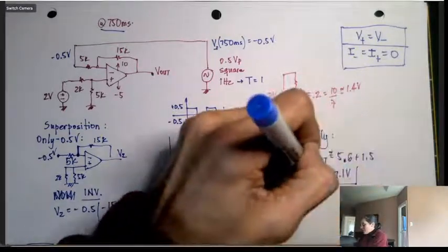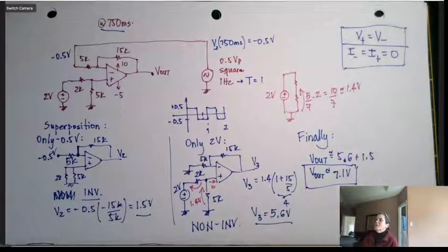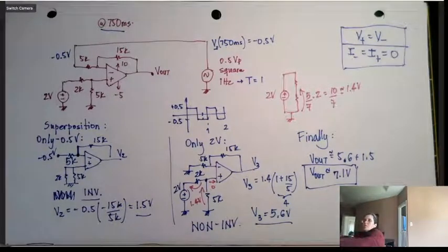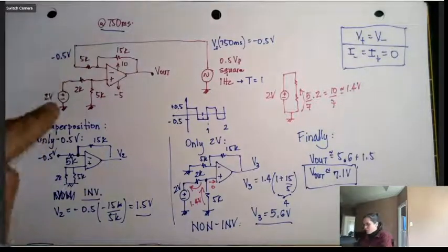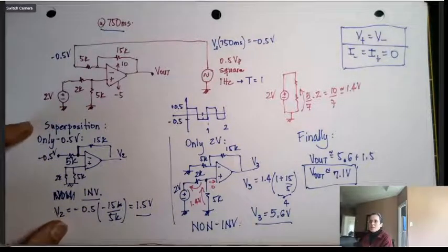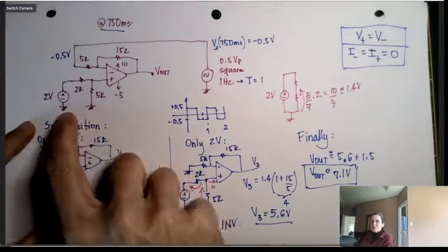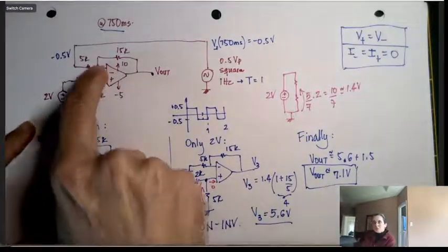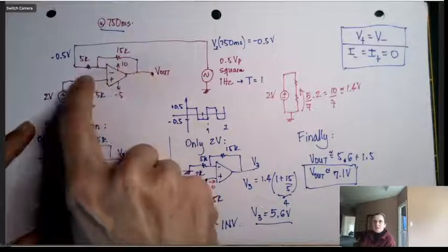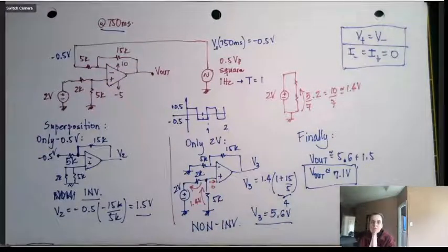I hope this helps, but if you would like me to answer any other questions, please let me know. I'm assuming we don't have a calculator. I'm also assuming we're going to do a lot of this. For example, if there are 2 power supplies, doing superposition from my perspective is simple, but you could have just put the 1.4 volts here and done KCL on it. So that's another way of solving the circuit without superposition.